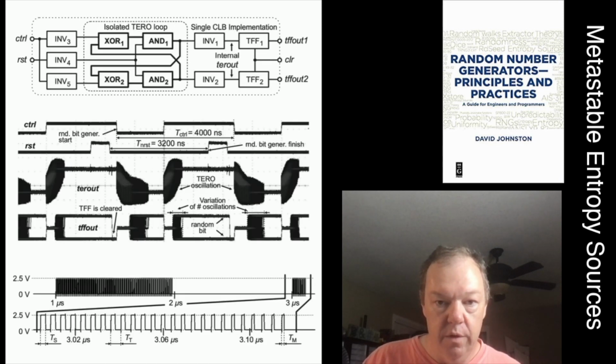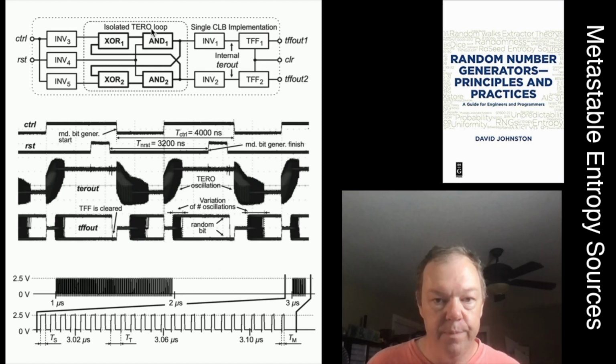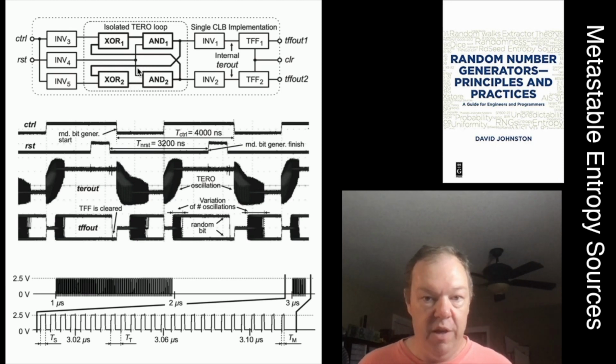So what they've done is they have taken an RS flip-flop, where you would have a NOR or a NAND and a feedback path, and that would be a flop which, when you put a 1 on one of the inputs and a 0 on the other, and return both inputs to 0, 0, the output will have switched, so one of the outputs is a 1 and the other is a 0, and it'll stay there.